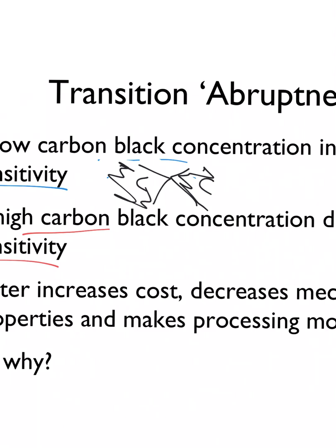All right. So if you're at 45% carbon content, you've got a ton of carbon contacts, and it's going to take more energy, more heating to destroy all of them to make this non-conductive, as opposed to 35%, which is going to be more sensitive. So it depends on the system you're protecting and how important it is that it be thermally sensitive. The latter will increase the cost because you're using more carbon black. Not like it's really expensive, but there is an increase in cost. But the main driver is it makes the processing more difficult.